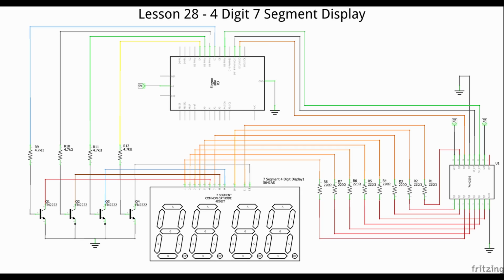Here's my circuit. As I indicated in lesson 27, it's better to provide resistors to each LED segment rather than using a common resistor for multiple LEDs. And since each LED can now have 14.5 milliamps of current, 8 LEDs would add up to 116 milliamps, which would easily overpower a single Arduino output pin if we were to use it as a ground source. To overcome the additional current draw and to save the Arduino output pin, we'll need to use a transistor.